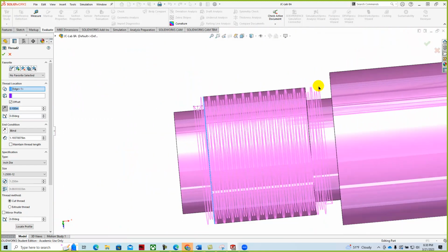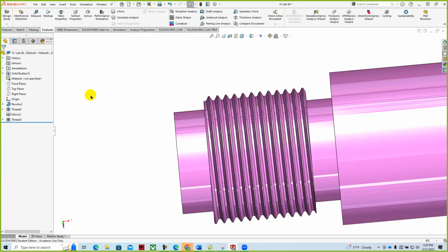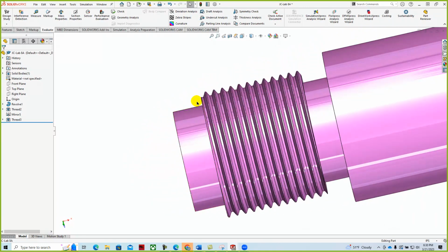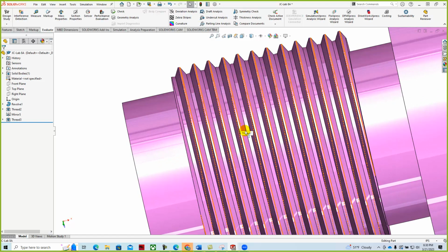part. And then this is a machinist technique where you'll create a relief for the threading tool so that as it cuts, it has a place to go and end and then come out, come back in, it'll feed, and then thread at a specific depth and RPM using a G97 G code to create thread. And so once we've done that, I can then green check mark it here. And now you can see the thread has a starting point. And so you can get the nut onto the threaded part.